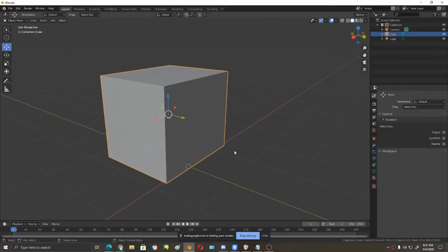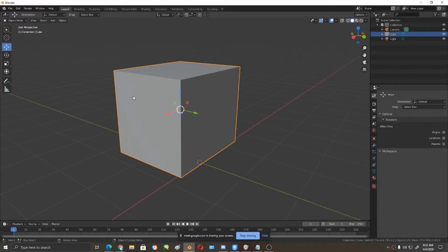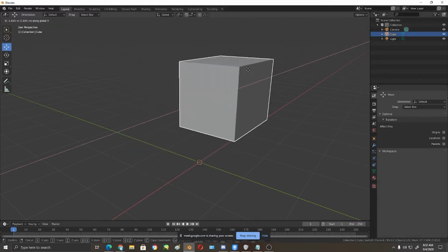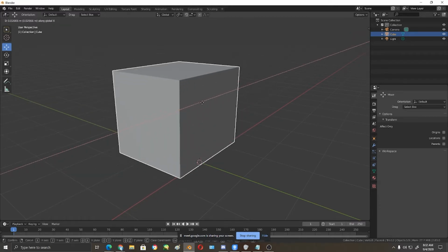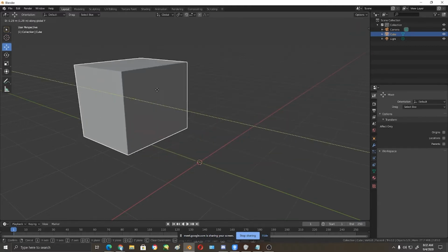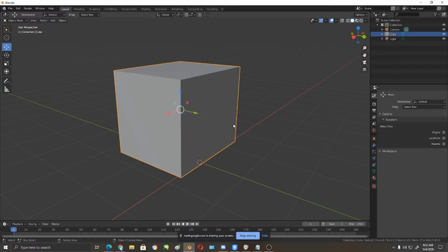Alright. So again, if we want to move your objects using the Move tool, the Rotate, and the Scale, press G. Press G, then press Z. Right click to let go. Press G, press X as a combination. Right click to let go. Press G, press Y, so you can move side to side. Right click to let go.